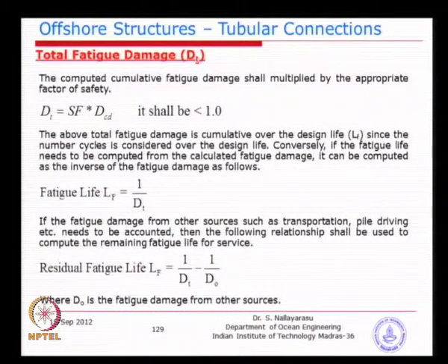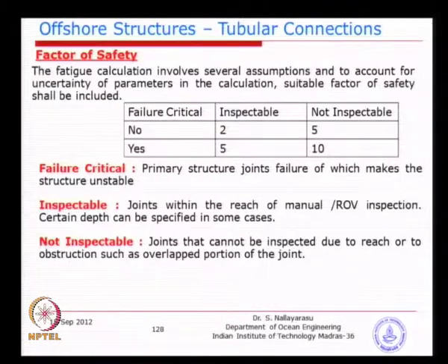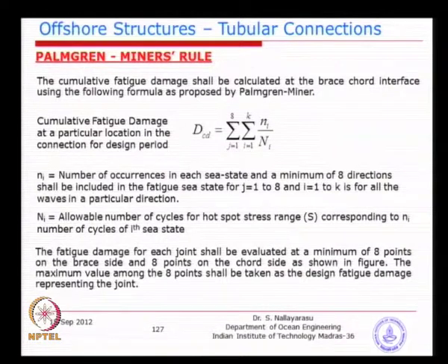So, basically what we have done is we have calculated the fatigue damage based on the number of cycles of loading and the number of cycles to failure, is it not? I think that is the fatigue damage. Now, this number of cycles of loading is based on a certain duration of the design life, so maybe 20 years, 25 years. If you have understood this, n is coming from the number of cycles throughout the design life.